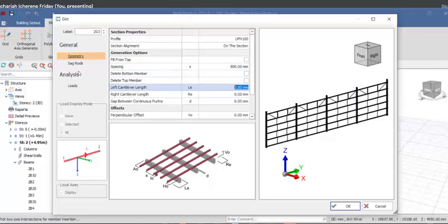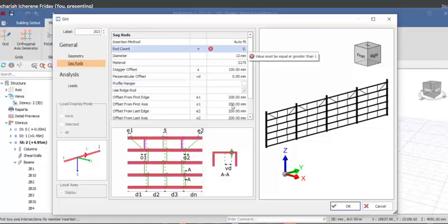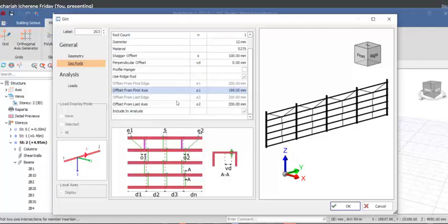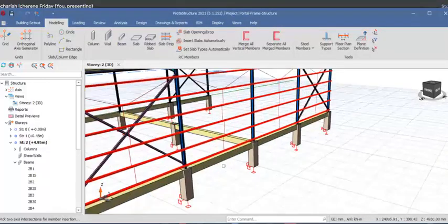After which you can get to the sag rod, you can get rid of this profile angle, and then over to these provisions. You can also get rid of the sag rod. Make the count 1 right there, like this. The diameter can remain the same, or you can make changes to it as well. After which, click on the OK option. So you now have something of this kind.